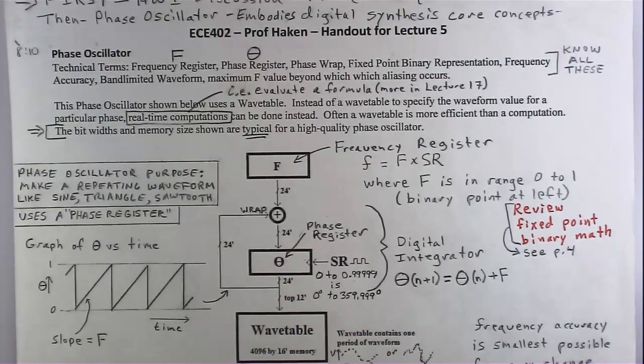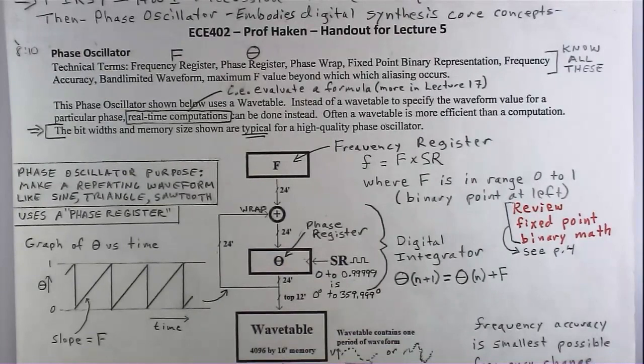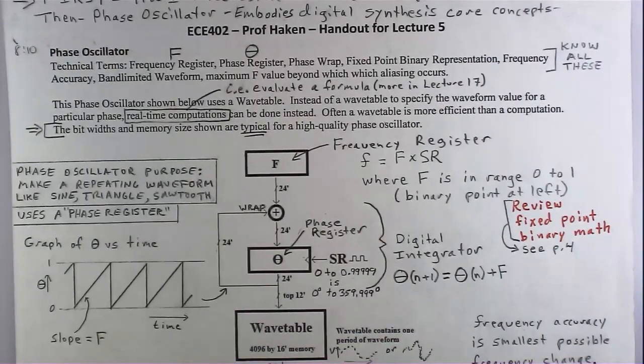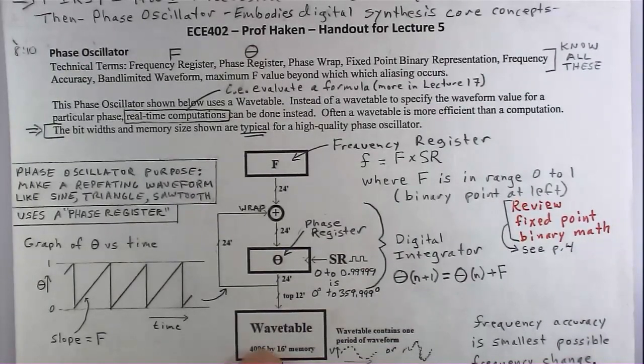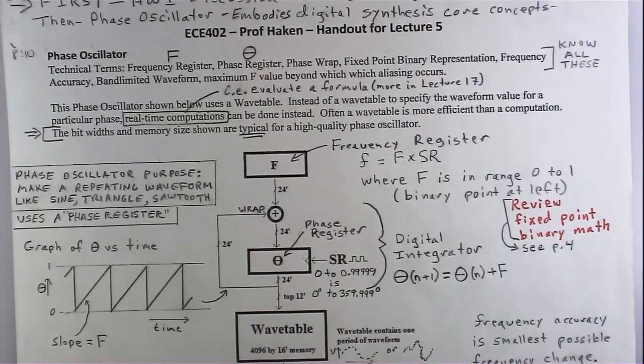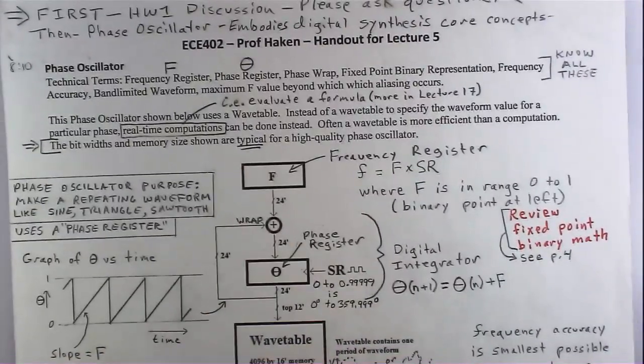Most important, for instance, the oscillators in the Haken matrix, there's granular-based ones, and there's lots of ways to make oscillators. You can do them with narrow bandpass filters and all sorts of other ways, too. But in the Haken matrix, the main oscillators that you use are actually not wavetables. They're math functions, a subclass of math functions called digital summation formulas. So they're not wavetable oscillators, and I needed some word for, hey, what are the issues in just a digital oscillator that has a phase register?